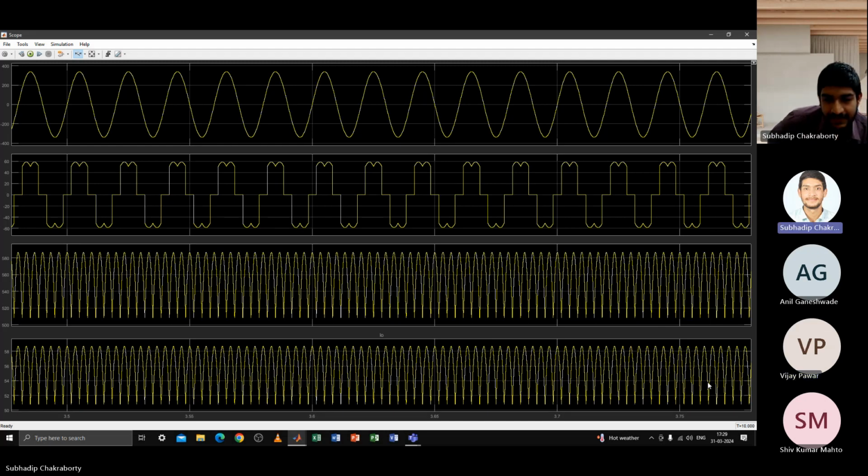Then answer what you think about that. Do you need reactive power compensation for these kinds of loads? Yes, sir, you take reactive power as well as harmonic compensation. No. This load, I told you, does not have any shift between the fundamental of the two, current and voltage. Then if there is no shift, where is the reactive power coming from? What is the definition of reactive power? The definition of reactive power is the shift between the fundamental of the two waveforms, voltage and current.